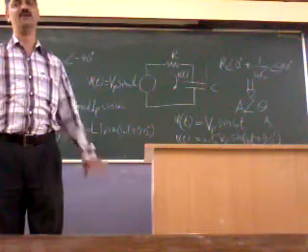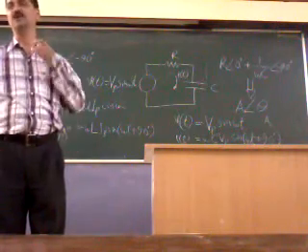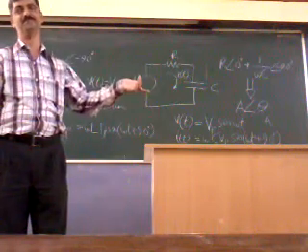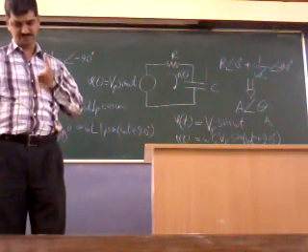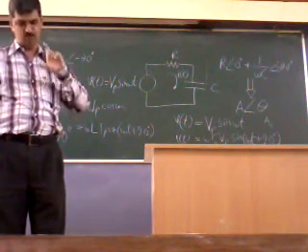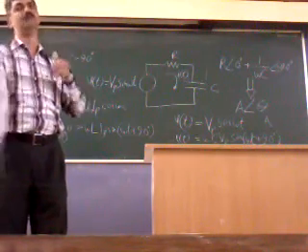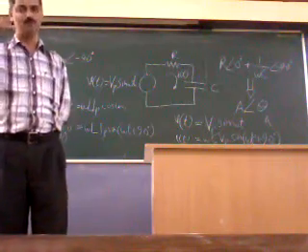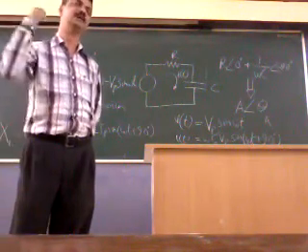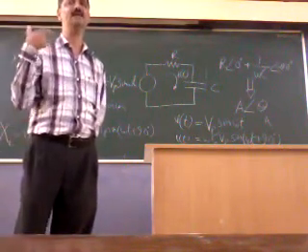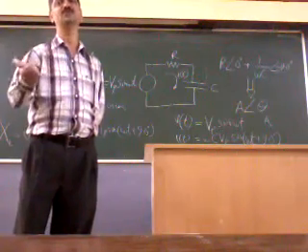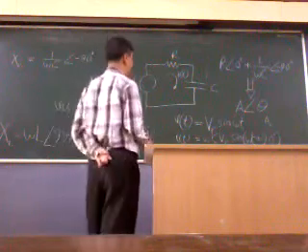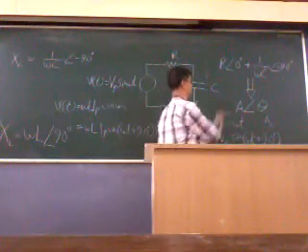Any relationship between voltage across 2 points and current, we can look at as the effective impedance. That ratio of 2 sinusoids of the same frequency can always be expressed by the ratio of their amplitudes and the difference of their phases. So now you are supposed to calculate A angle theta. You have to calculate A and theta.